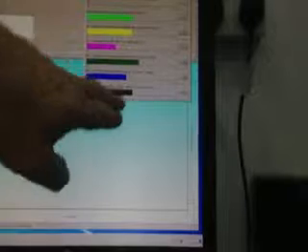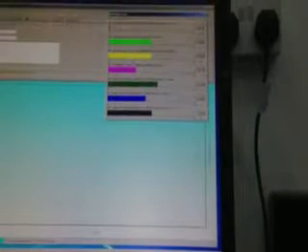Very low or? It does not have to be exact. You need to work out how much movement the transducer will do. Because you're targeting 100 microstrain, it's only a very small deflection on the sample. So as long as you're within the middle of the transducer, you do not need to be exact, but around that area, it should be okay.